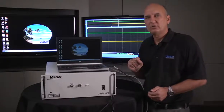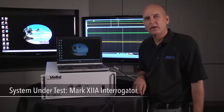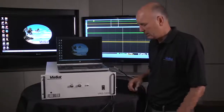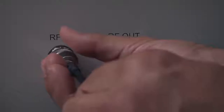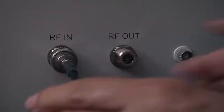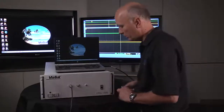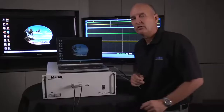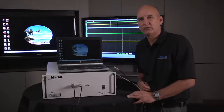The second connection is going to be to our system under test. Our system under test is a Mark 12A interrogator. We're going to be taking the RF output of the Mark 12A interrogator, connecting that to the RF input of the ViaG1000. And then the ViaG RF output is connected to the Mark 12A interrogator's RF input. If your system has a single input-output connection, then we put a circulator onto the front of our system to separate the RF into input and output.